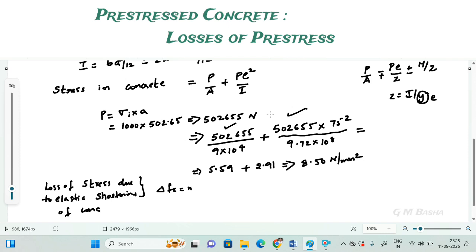So you please remember this formula: M into stress value. So this is the stress in concrete, M into sigma. That one will be equal to how much? This M will be equal to modular ratio. How will it be found? In the question only, they will give the data ES and EC value. So modular ratio, you please remember this formula, M equal to ES by EC directly.